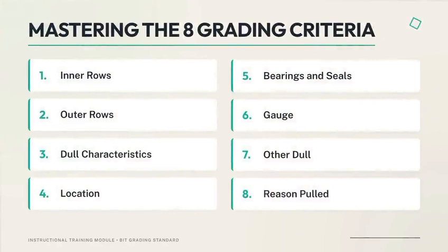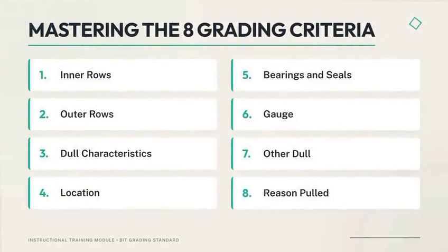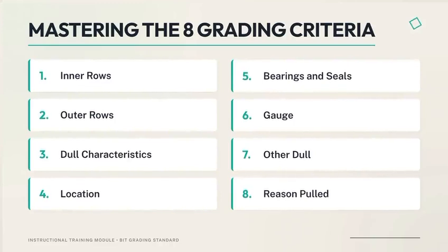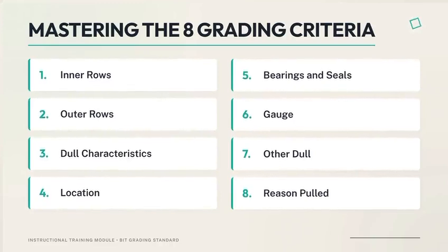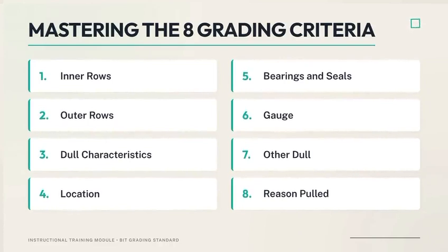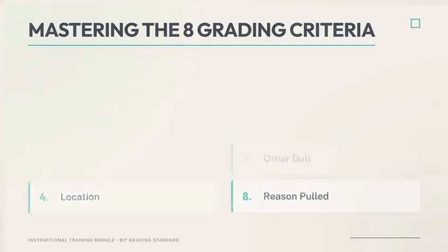format. We will learn how to measure tooth wear, identify specific failure modes, determine the precise location of wear, evaluate seal integrity, and accurately measure gauge reduction. Let's start with test number 1, the inner rows.